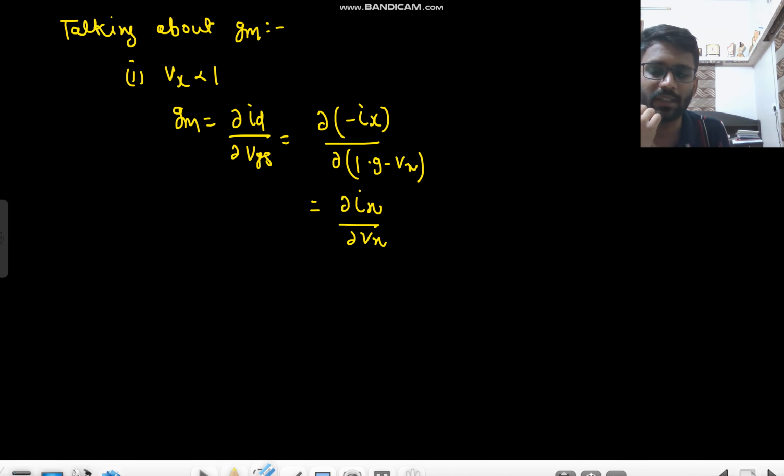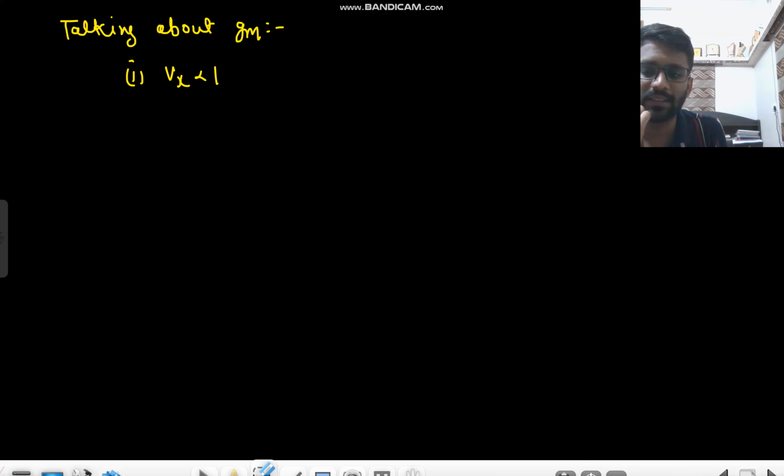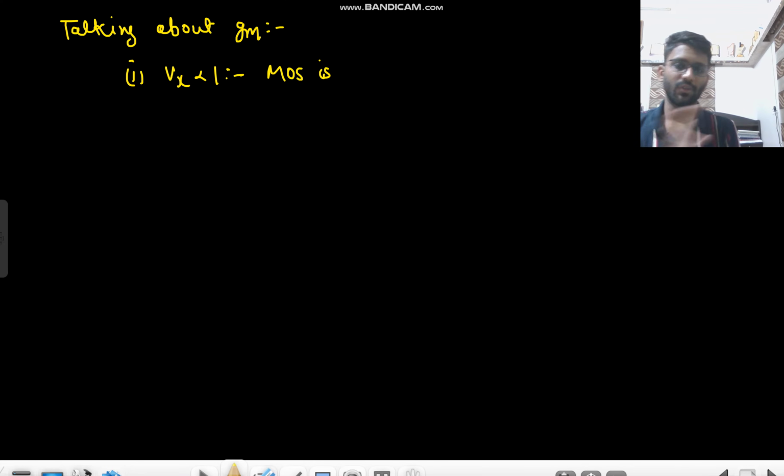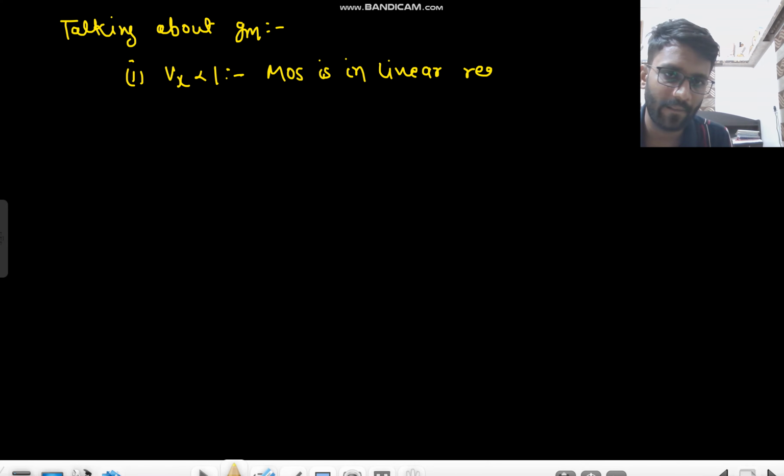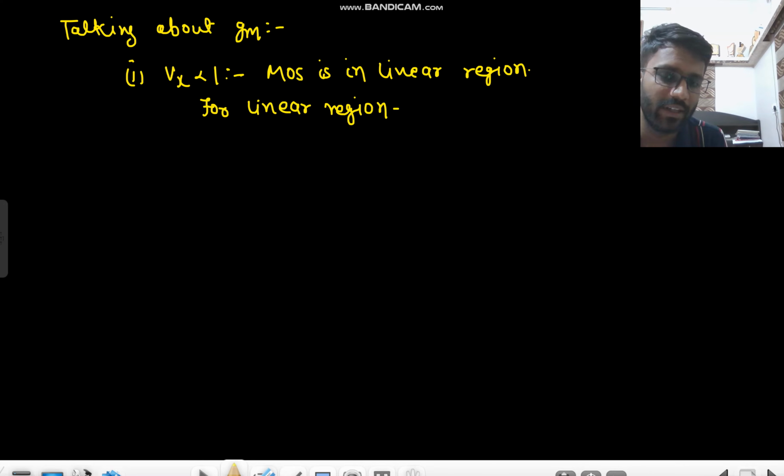But what you can also do is, for Vx less than 1, you know the formula of gm, right? I have already told the concept of gm. If you do it by the other concept, you will make many mistakes. So you just need to see the region of operation. MOS is in the linear region. For the linear region, what is the formula of gm? For the linear region, not for saturation. gm is mu n Cox W by L VDS, right?